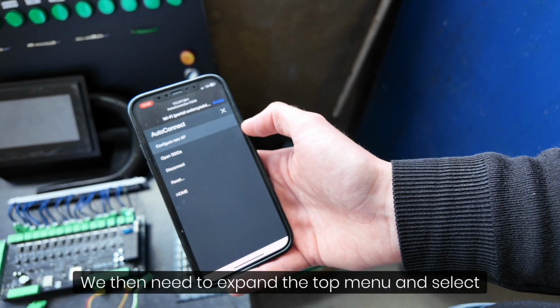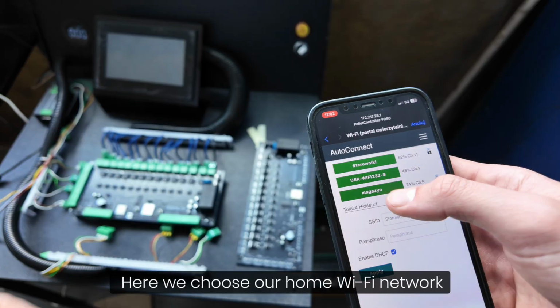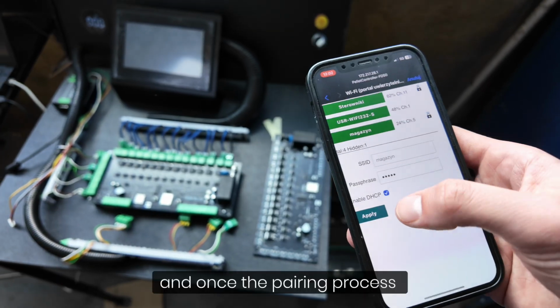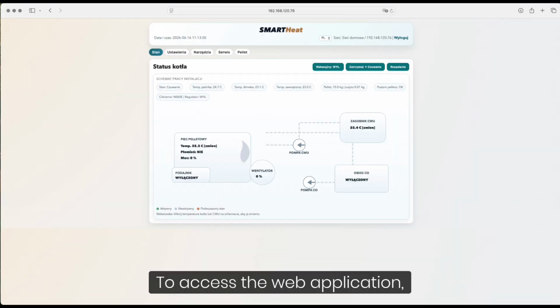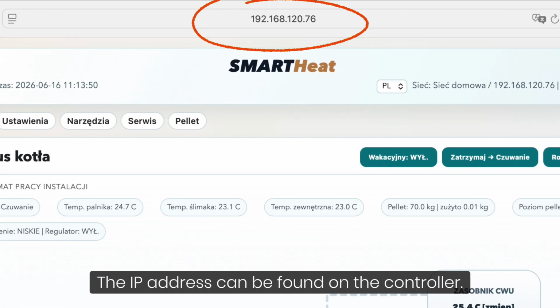We then need to expand the top menu and select Configure New AP. Here, we choose our home Wi-Fi network and enter its password. Next, we click Apply. And once the pairing process has been completed successfully, the controller will be connected to the internet. To access the web application, enter the IP address of the controller into the browser's address bar. The IP address can be found on the controller.